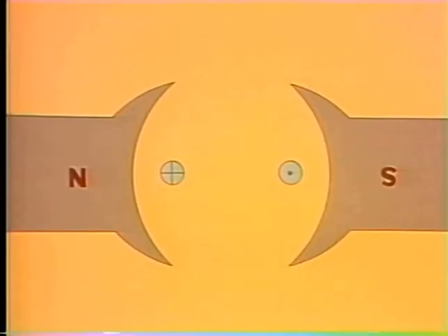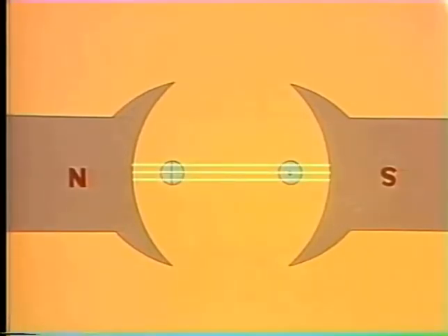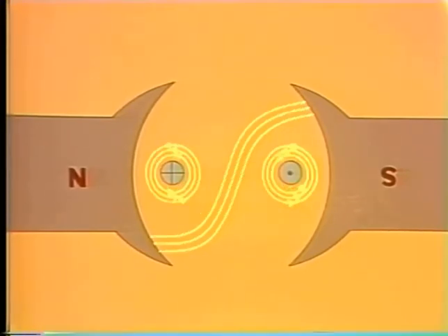Now, look at this end view of our conductor and the main magnetic field. Current flow goes into the conductor here at the cross, or back of the arrow, and out here at the point of the arrow. Now, the smaller the load, the less current there is flowing through the conductor. That means there's a smaller field around the conductor too, so the shift in the main field would be less. As the load gets heavier, more current flows through the conductor, and it has a bigger field around it. So it causes a greater shift in the main field.